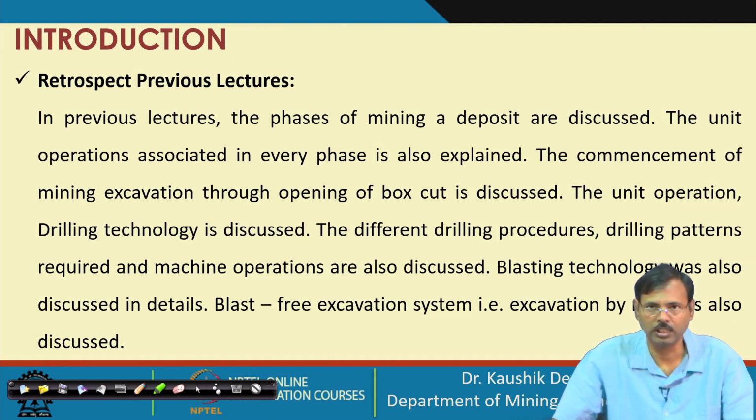Then we covered unit operations like drilling technology, and we discussed different drilling patterns. We discussed the blasting technology, which is most commonly used for fragmenting the rock mass. After that we covered blast free excavation technology, which is adopted for soft material, that is ripper, and how the fragmented material can be excavated by the excavator or loaded to the transporting system.